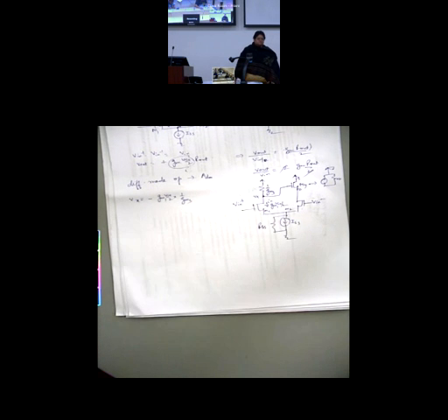So the drop here will be minus gm times V in by 2 into 1 by gm3. You may say this has to be RO coming from here. Then why RO? Find out the net R out here.